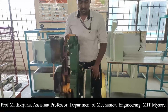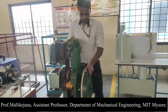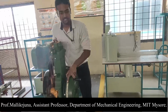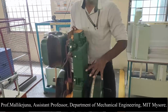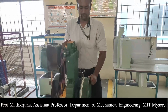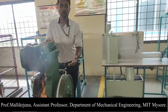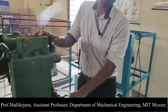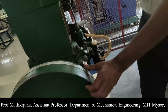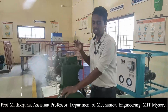So I will adjust the things in such a way that I will be at suction stroke now. Before that, make sure this is the TDC point, and exactly half a rotation, I mean 180-degree rotation, will give us the BDC point. This is the BDC point, and here we have a pointer. With the help of this pointer, we will be looking onto positions, TDC as well as BDC. With respect to this, we will be fixing TDC as well as BDC. Now I will adjust the flywheel so that I will be in suction stroke.